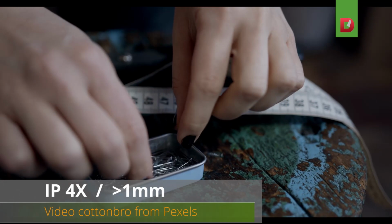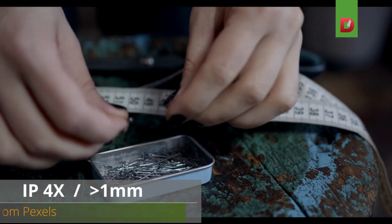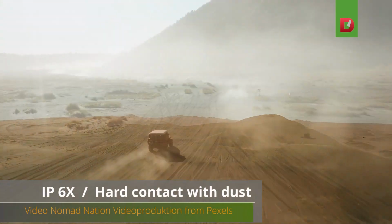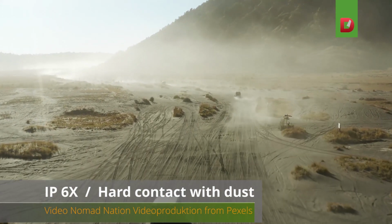Number 4 is protection against dangerous solid parts that are 1 mm or larger. Number 5 is protection against dust-limited ingress, no harmful deposits. And finally, number 6 is complete protection against solid materials, like against hard contact with dust.